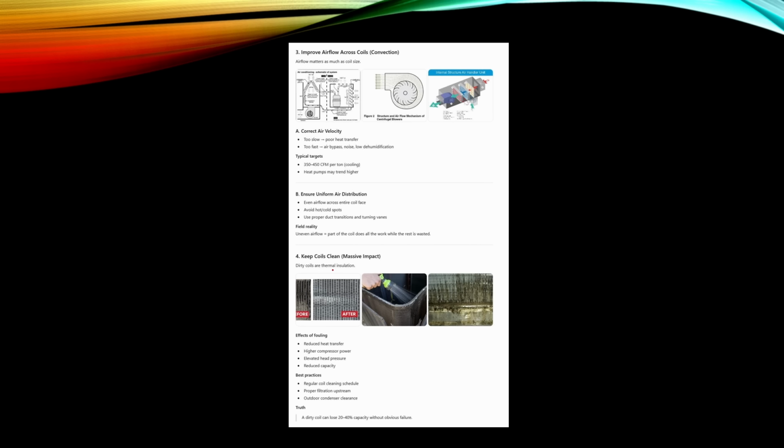Here is another example in which we typically have problems with deposition formation, and we need to keep those coils always clean. Regular cold cleaning is needed in many cases when we have some particles in our air or gas flow.